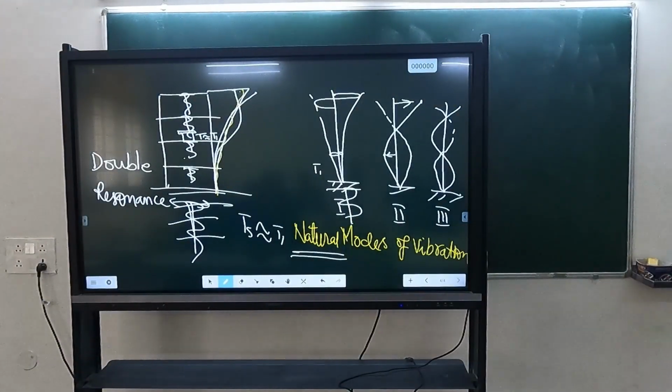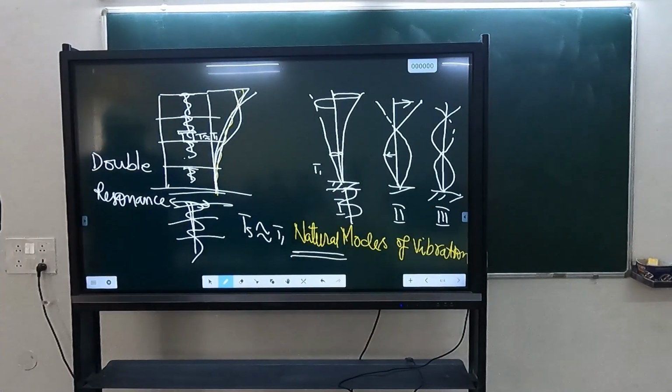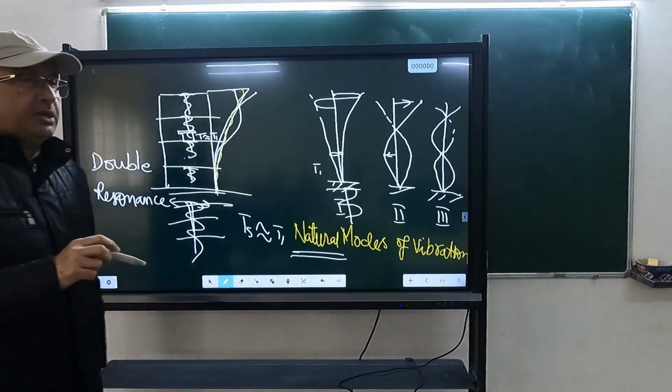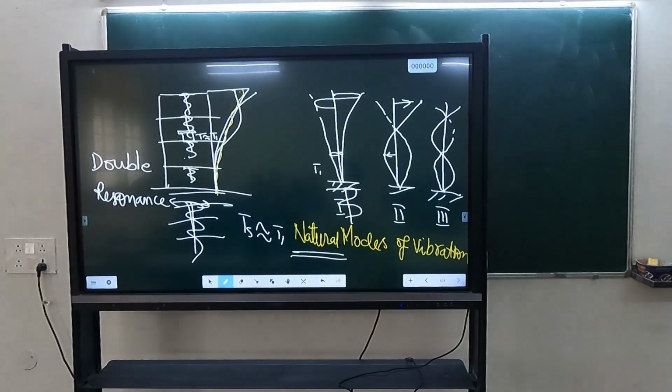The frequency of the secondary component matches with the frequency of the structure, which again matches with the frequency of the soil. So you have to be very careful about those secondary elements which have their frequency close to the fundamental frequency of the structure.